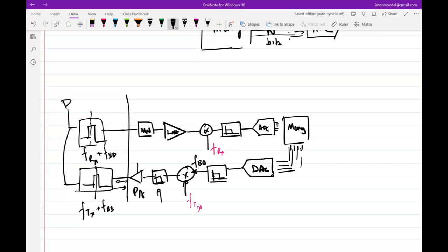It is called load pull. Just think of it as tuning the output impedance of the PA to operate at maximum efficiency, ensuring there are no untoward effects of reflection. There will be reflection, it is understood, but you have to place whatever things you are placing outside the PA in such a position that they do not cause adverse effects to the PA. That's the trade-off. But you are correct. Ideally, we should have put a matching network, but a matching network has that trade-off of losing power. Could as well modify the output impedance of the PA? To some extent we do, but it's not in our control what is after the PA.